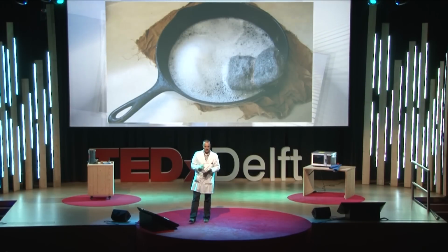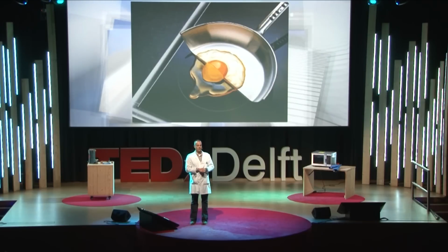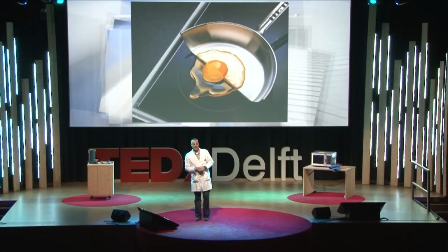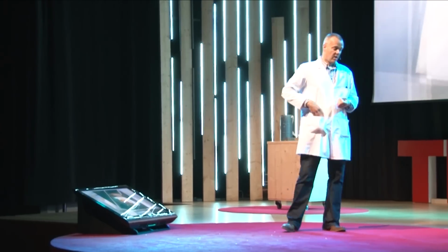Then you need a machine, like you see here, that you can use for cooking. An induction machine. Induction can heat, especially steel, it's very good in that. And then what you do is you heat up the steel, you melt the bitumen, and the bitumen will flow into these micro cracks, and the stones are again fixed to the surface.